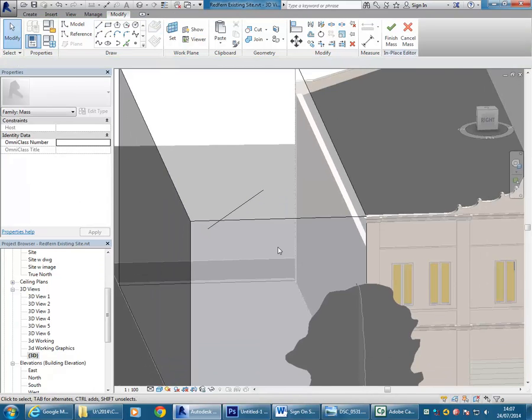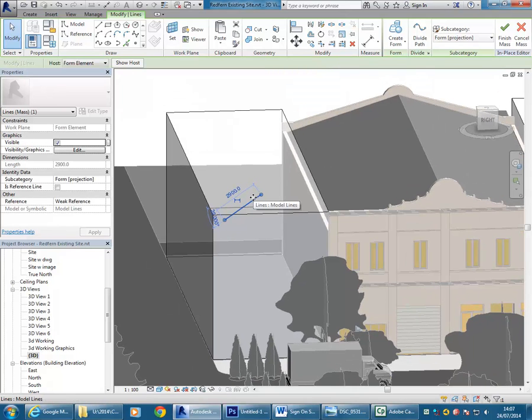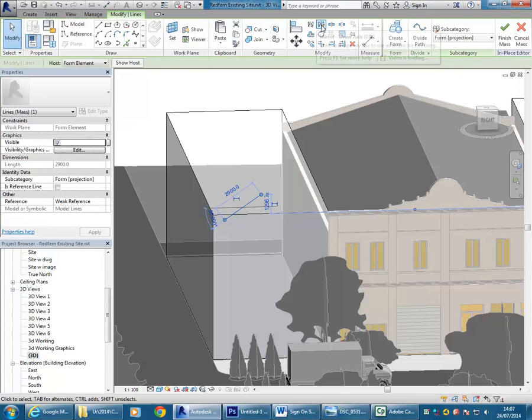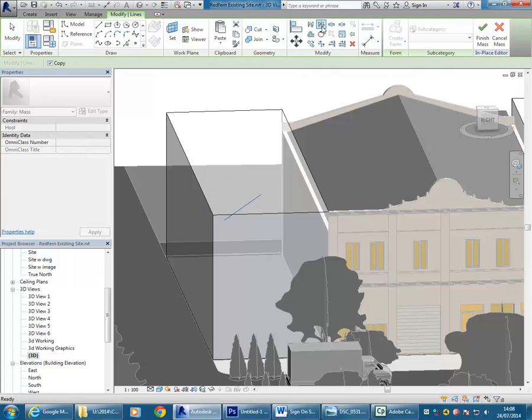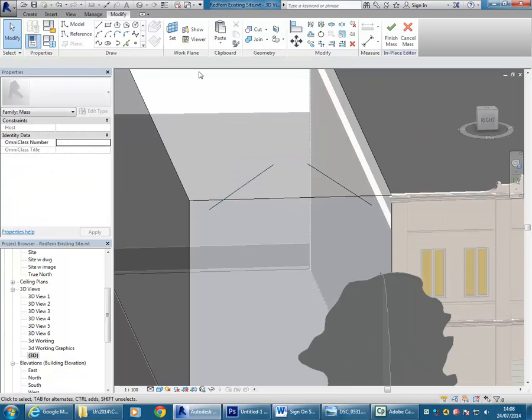And this time, because I want to make that symmetrical from the beginning, I'm going to select the line. So I've just cancelled with Escape to finish drawing. I can select the line then and use Mirror Draw Axis and simply snap to the midpoint of the front there. Take it up or down, doesn't matter which way you go, as long as it's 180 degrees to give you a straight, horizontal. Okay, so I've got a symmetrical copy, which I can join using Trim to the first one. Notice how now they come up as one shape.